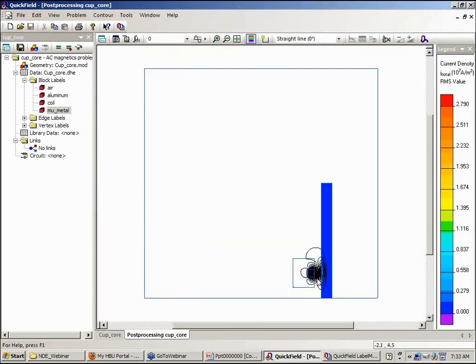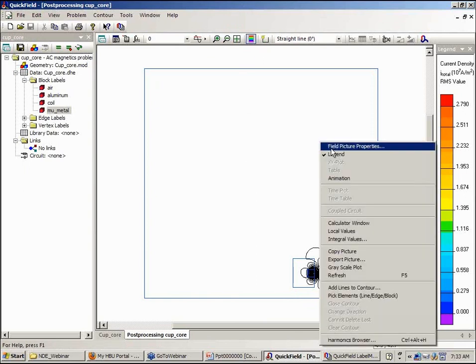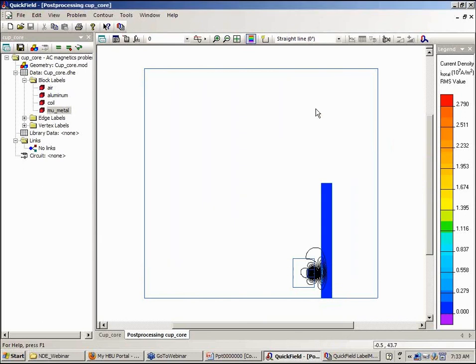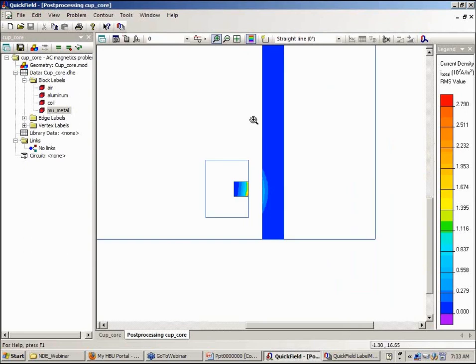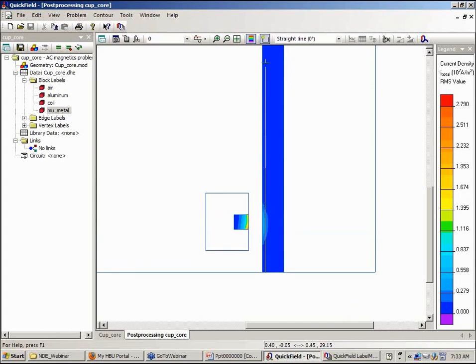Now, in this simulation, you can see that the magnetic field is screened in the external regions here. However, the flux density is increased beneath the ferrite, and we can plot the eddy current density and compare with and without the ferrite. I will go ahead and turn off the field lines. Zoom into the problem. I will create a contour beneath the surface here. Okay, I'm creating the contour by hand.